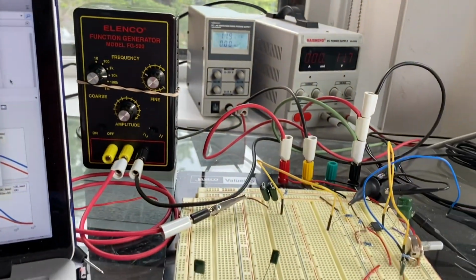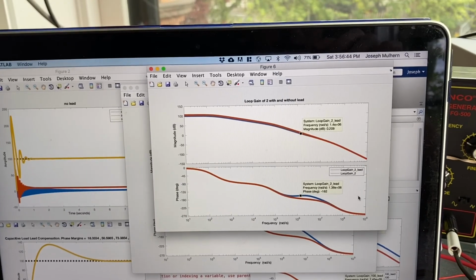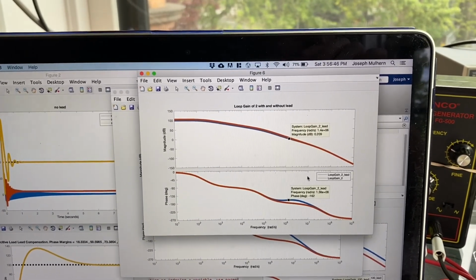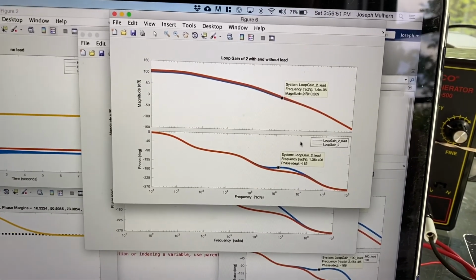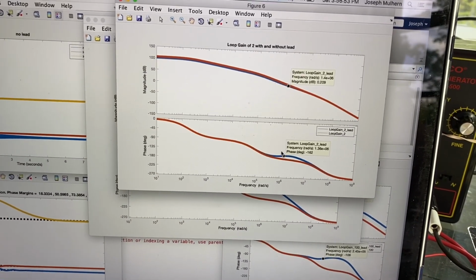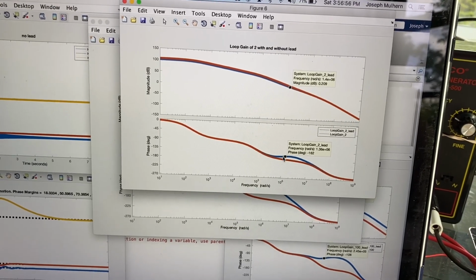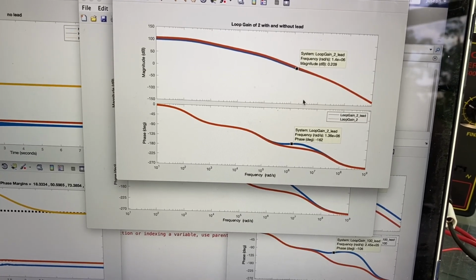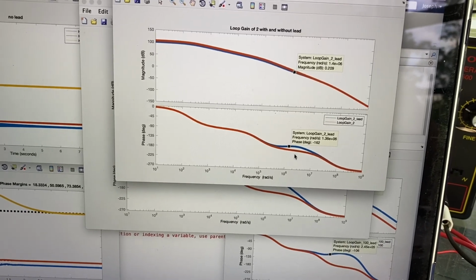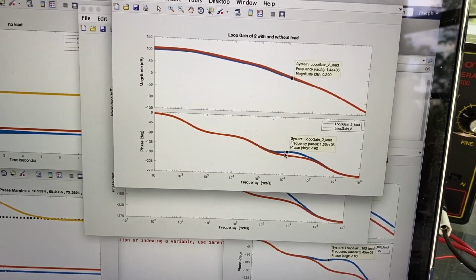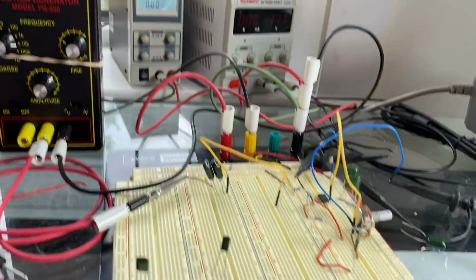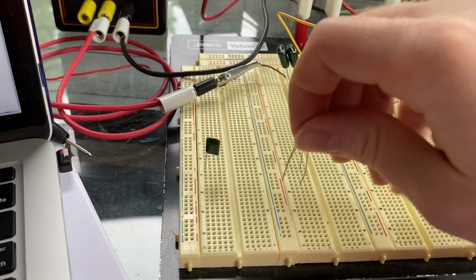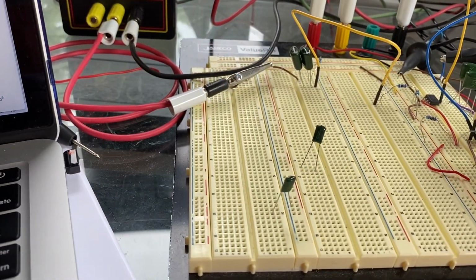And so we can go and look at, here's a gain of 2. So I have a 100 ohm resistor, feedback is R2, and 100 ohm from the inverter terminal to ground is R1. And we see this is the hardest to compensate. Voltage buffers and low gain are hardest to compensate, but we still, if we locate this new capacitor so that our 0 is over the old pole, we have a little bit extra phase shift. So in that case, I have this capacitor here, which turns out to be proper.